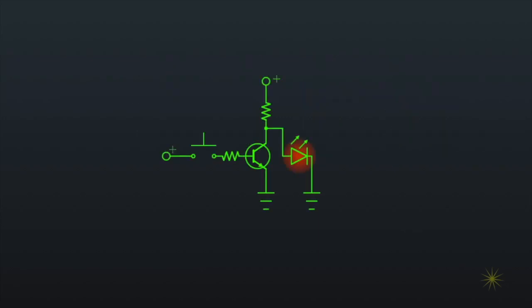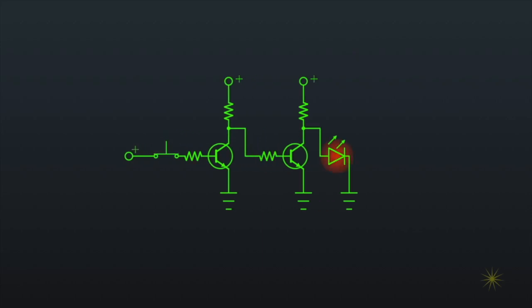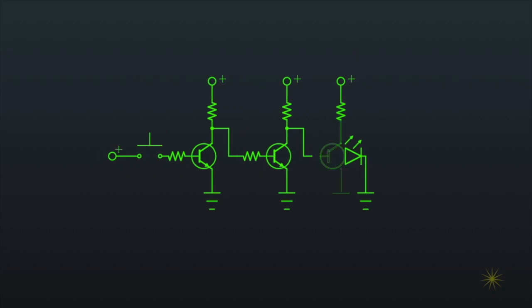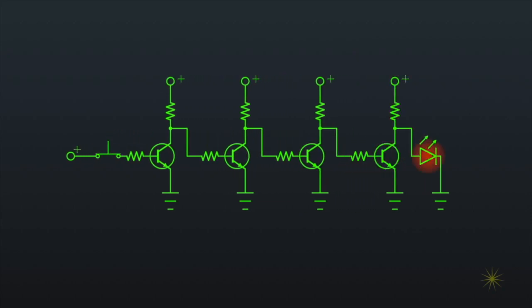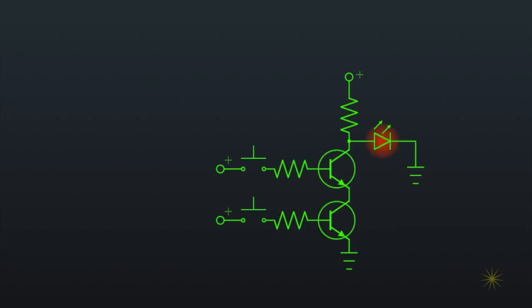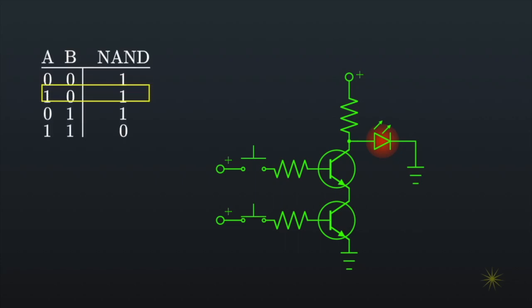This is where the amplification properties of a transistor come into play, because if the on or 1 is not fully on, the next gate down the line will amplify the results rather than dropping the voltage to the point where the circuit fails. So what are we to do? Well, we can go back to the circuits we know work because the transistors are inserted between the resistor and ground. We can start with our NAND gate.